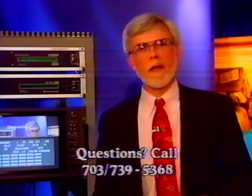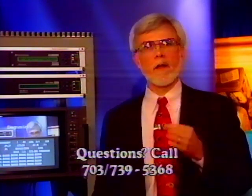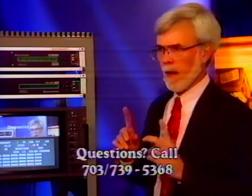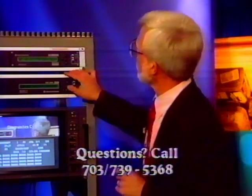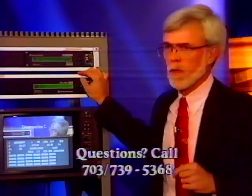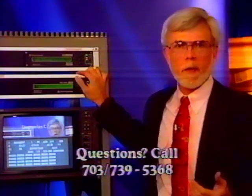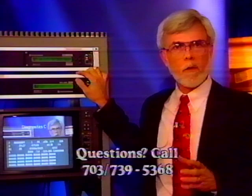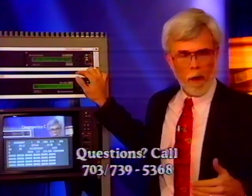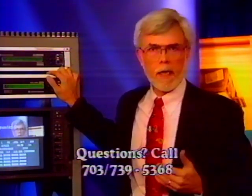I can take that one. It will be much easier for you to take your IRDs back to the factory reset position, and I'm sure you know where it is, Spence, but for those who don't, it was what I did to get us started today, and it'll just save a lot of time, because once again that blows out any of the channel maps that may be present in the IRD from SBS5, and they are different when we go to GE3, and so rather than take a chance of getting a convoluted channel map or one of those type of things, you're probably better off just to take it down to the factory reset and begin again.